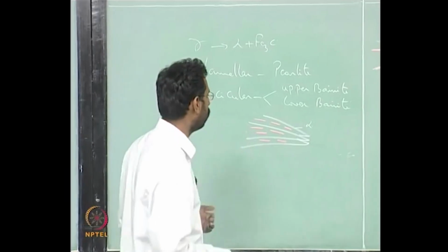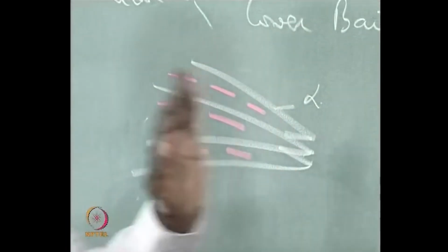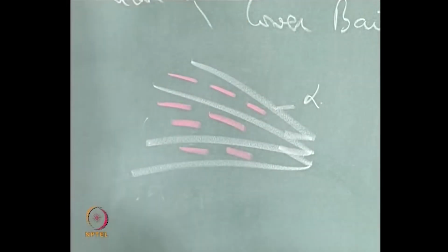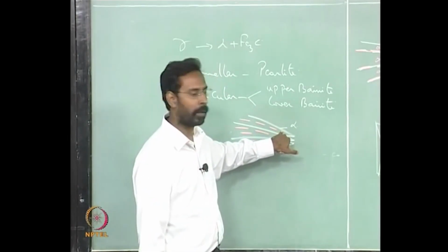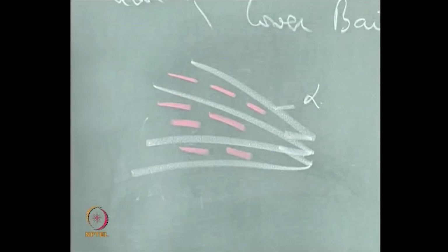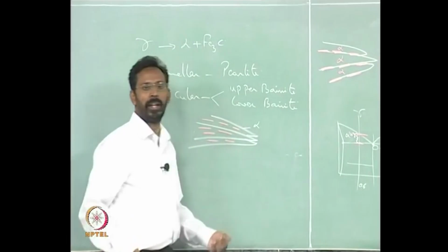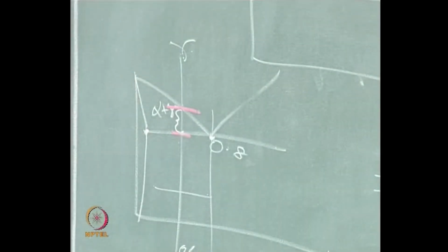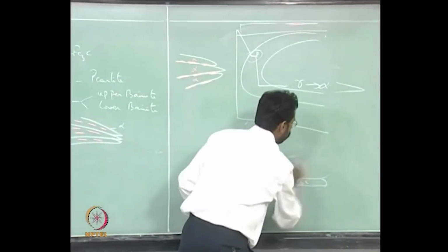But if you have plain carbon steel and the transformation is done at relatively higher temperature for a long time, then all the excess carbon will come out as cementite, and you would see the ferrite having, let us say, 0.025 composition, and the cementite there according to the volume fraction it is supposed to have. Okay. This is how you would see transformations taking place.